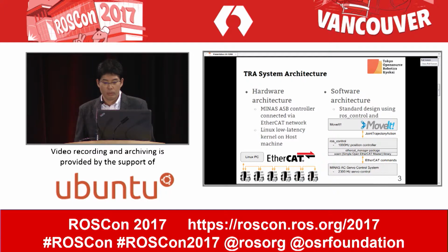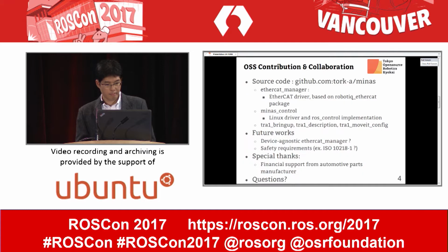So we wrote a driver for the EtherCAT drivers, and we can make it very simple, and we can use it with the MoveIt high-level controller. We have now released it for Indigo, and the source code is available here, and a video is online on our website. So please consult them.